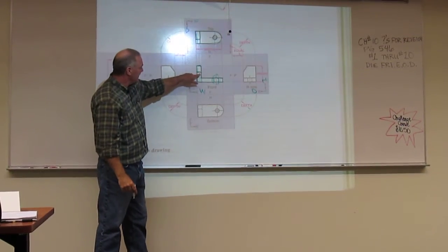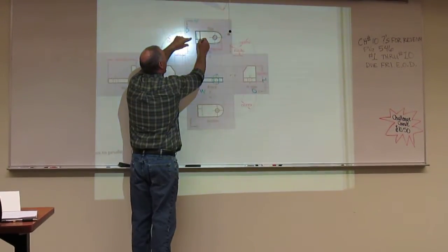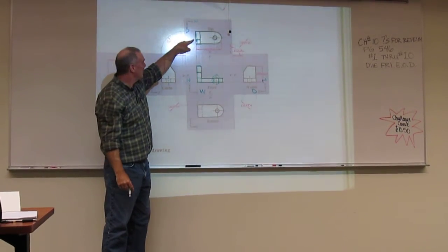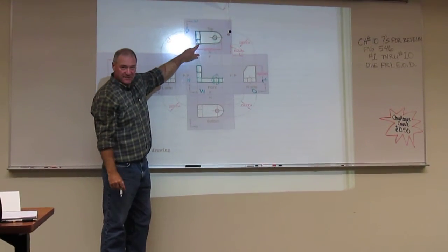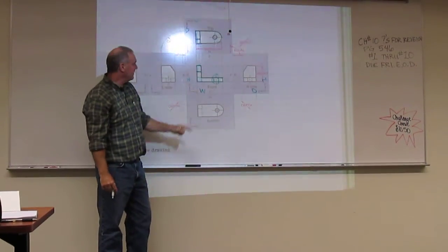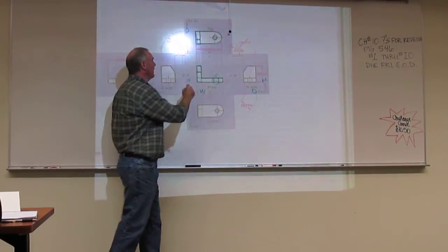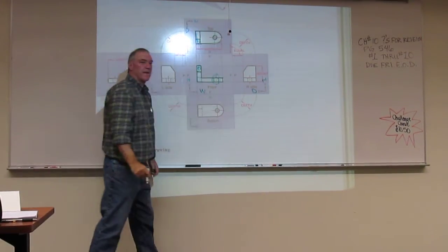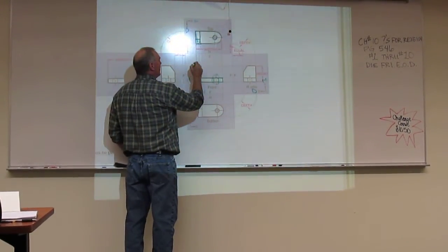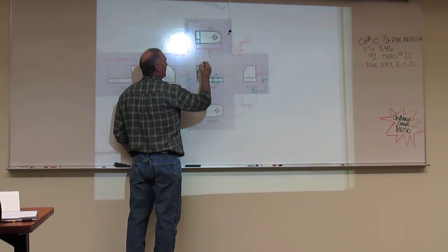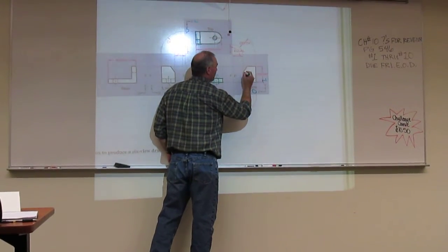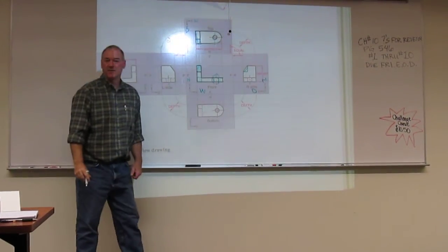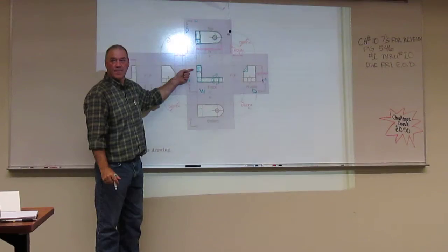The next part we have is this last rectangle right here. This one, we see the width, we see the height. Up here, you see it right here. That gives you depth. And it also gives you your width, but we don't have the whole story here. Based on these two views, since it is inclined, this top part is foreshortened. That thing could still, at this point, be a circle. It could come up, or it could do this, or it could do that. It could do all of those based on what you see here and here.